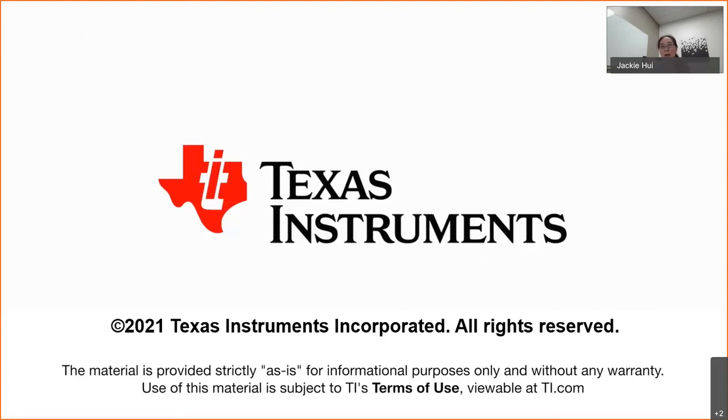Now, with that said, I would also recommend, if you do a new design, you want to have placeholders in your components. For example, even if you don't decide to use a gate resistor, do put a 0 ohm placeholder in there for your initial evaluations.